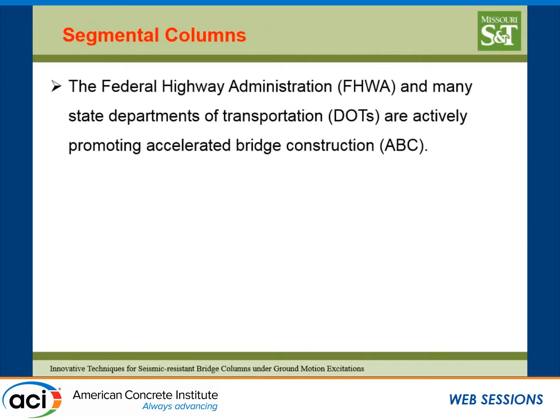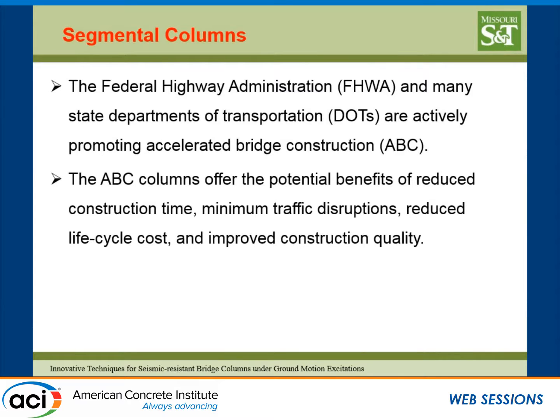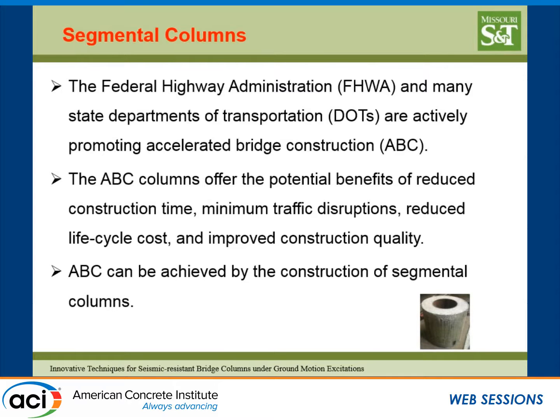And now we move to the external solution, which is the segmental construction. I'm not going to repeat what you heard before in the first presentation. With accelerated bridge construction, there is strong momentum right now in the US to develop it, and you get all these benefits here. The cross-section that we decided to use is a hollow core section. On the outside, we have a fiber-reinforced polymer tube, on the inside we have a steel tube, and in between we have concrete.